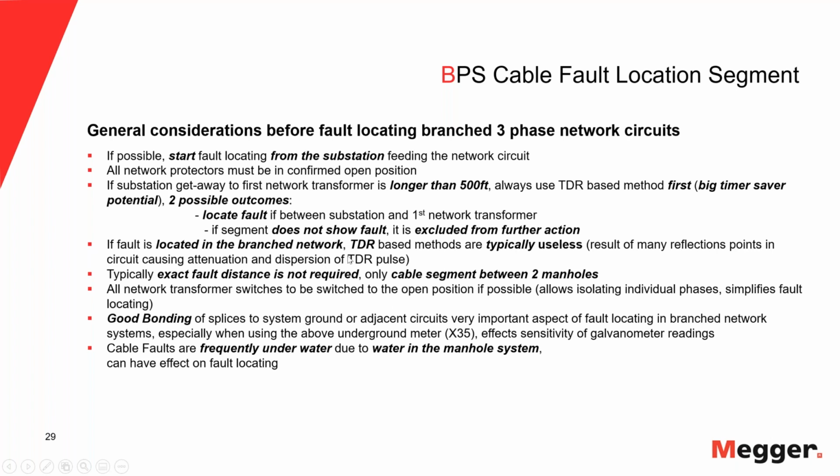Okay, so also what's important to recognize in these type of networks, we don't need to know the exact fault distance, because we're looking for the faulted cable segment between two manholes. So the distance is not that critical, and so what's also important is, obviously, if we can switch the transformers in that open position, we should always try to do that, because that allows us to isolate individual phases in the system.